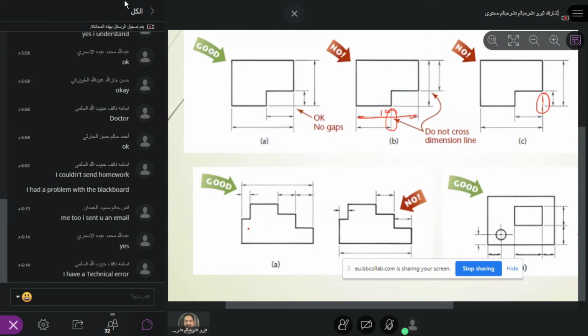And then for this particular shape, how to draw the dimensions. Now you see the larger dimension is on the far end, followed by the smaller one, and so on. But see here, this is not on the same line, so this is not a very good practice. Although this is correct, it's not a very good practice. You won't get marks for it. So these dimensions should be placed in one direction or a particular orientation. The orientation is very important to make it easier.